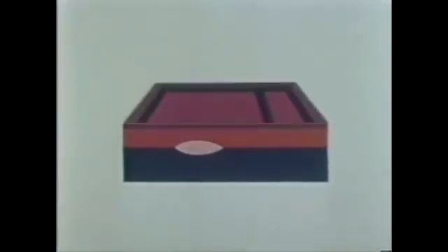Now we form electrically isolated regions on the wafer by a process of diffusion, photosensitive coating, masking, exposure, rinsing, etching, and diffusion. Next, we prepare the individual parts of the integrated circuit. First, a transistor base and a resistor. The same procedure is followed. Notice that diffusion takes place not only downwards, but also laterally under the oxide. As a result, the junction is formed beneath the passivating layer, where it is protected from the outside world. The next diffusion forms an emitter and a collector contact to complete the transistor. Again, the same process.